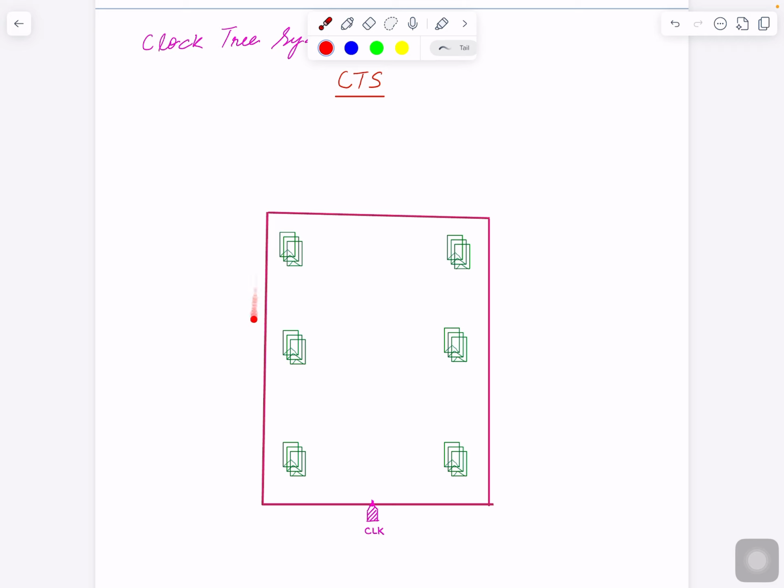So here is one partition, let's say it has this X-Y size. The clock comes at the port, or actually the terminal, of the partition, and what happens before that is taken care of by the top level. Or this is a small chip that you are taping out, and it's not a hierarchical design. In that case, this chip is your block, and you're not doing any additional clock distribution. From the pad, your clock comes here. So let's say this is a pad, and then it will be distributed to different parts of the chip. So I'll just give you a picture here.